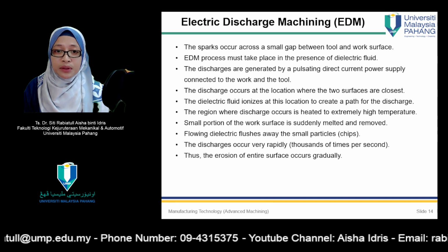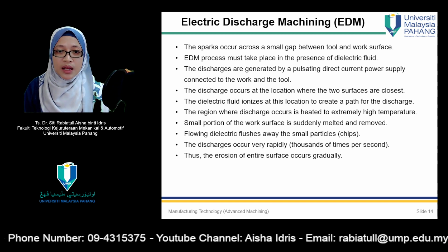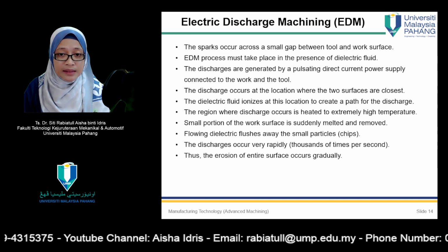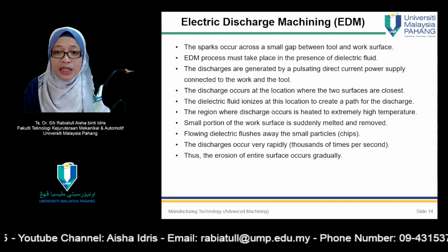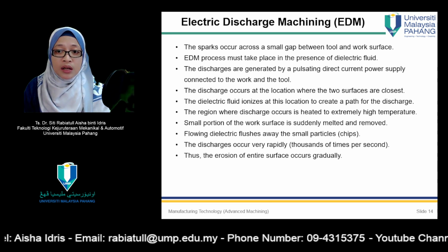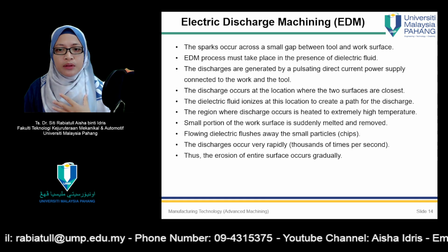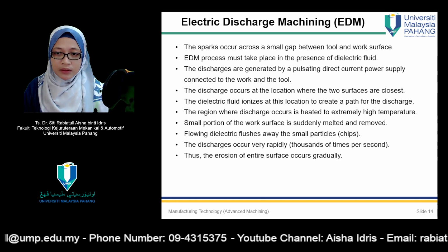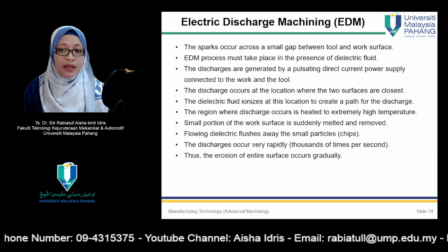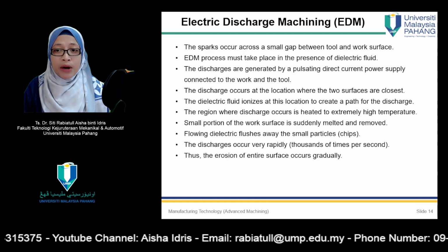The flowing dielectric then flushes away small particles because the surface of the work at the location of the previous discharge is now separated from the tool by a greater distance. This location is less likely to be the site of another spark until the surrounding regions have been reduced to the same level or below. Although the individual discharges remove metal at a very localized point, they occur hundreds or thousands of times per second, so that a gradual erosion of the entire surface occurs in the area of the gap.